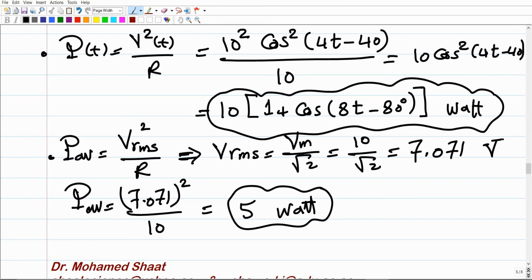In the time domain, when we analyze the electrical circuit, we end up with differential equations, and if you have multiple differential equations, it's much more difficult to solve them analytically. But if we move the electrical circuit to another domain, and we're going to show you how to switch to it, we end up with linear, simple algebraic equations. There are no differential equations anymore, so we can solve these equations analytically. This is what we're going to do through this chapter.